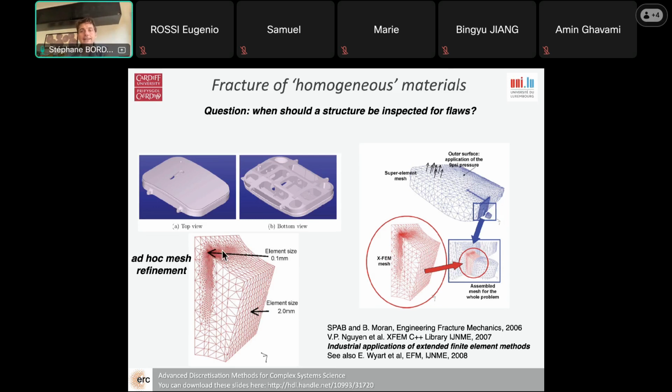But very quickly I realized that all I was doing was very limited because I was initiating the crack here and the crack would grow. It will grow approximately in the plane, which means in that plane here, because the load was approximately tensile. So it would open the crack and it would grow. I was lucky because I put enough elements along that plane, which you also see here and there. But the problem is, in reality, I cannot know in advance where the crack is going to grow, right? Otherwise, if I knew, there would be little need to compute anything.